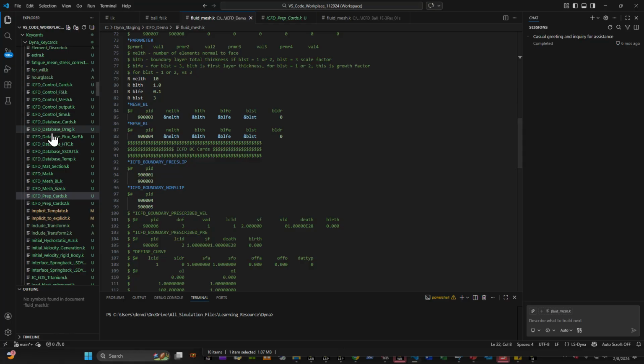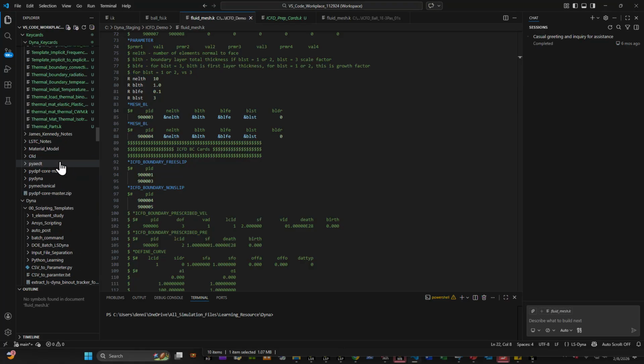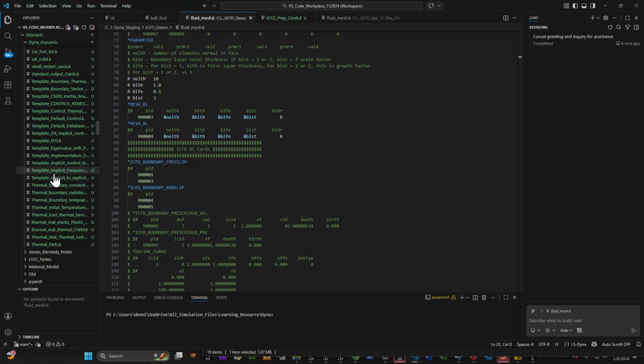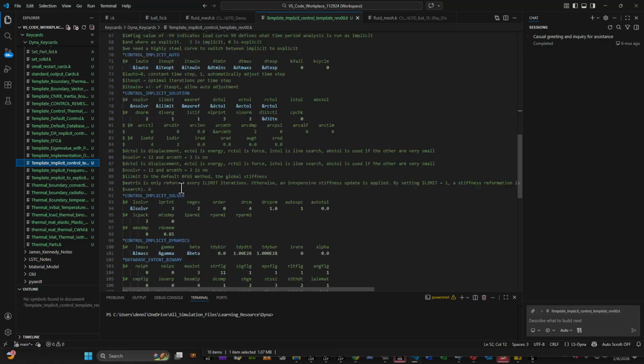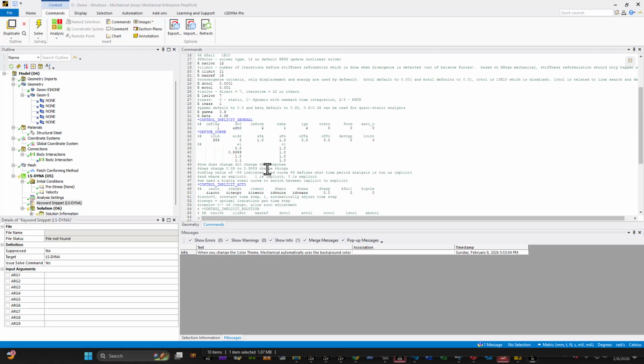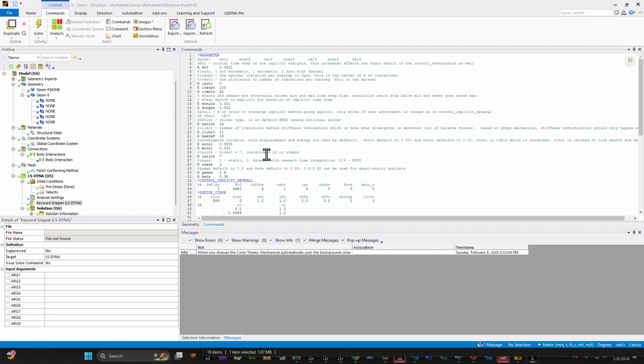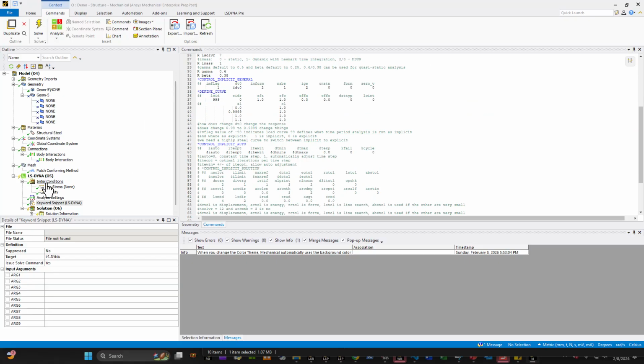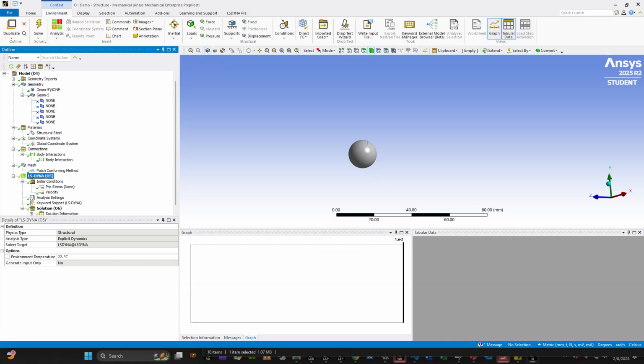Basically, I have an implicit code template. My implicit code template handles the setup for implicit analysis relatively well, right? I'm trying to look for my implicit template. Yeah, right here. This is my implicit template, right? So I just copy something similar over here. This implicit template basically allows you to set up this problem as an implicit analysis, and I have the same time step as my fluid side. I'm making sure it's not automatic, and I just solve implicitly. It's actually really simple in this case.